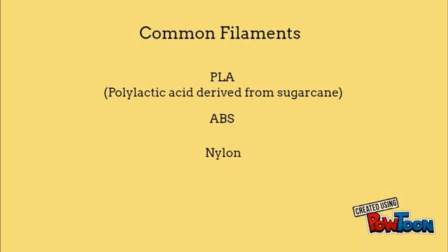Nylon is generally more expensive and requires a printer capable of higher print head temperatures, and it's used in specific applications where its wear resistance, durability and low friction coefficient make it suitable for mechanical parts, gears, bearings and other objects under load. Nylon filament is also very hygroscopic, and for satisfactory printing it must be dried before being used.